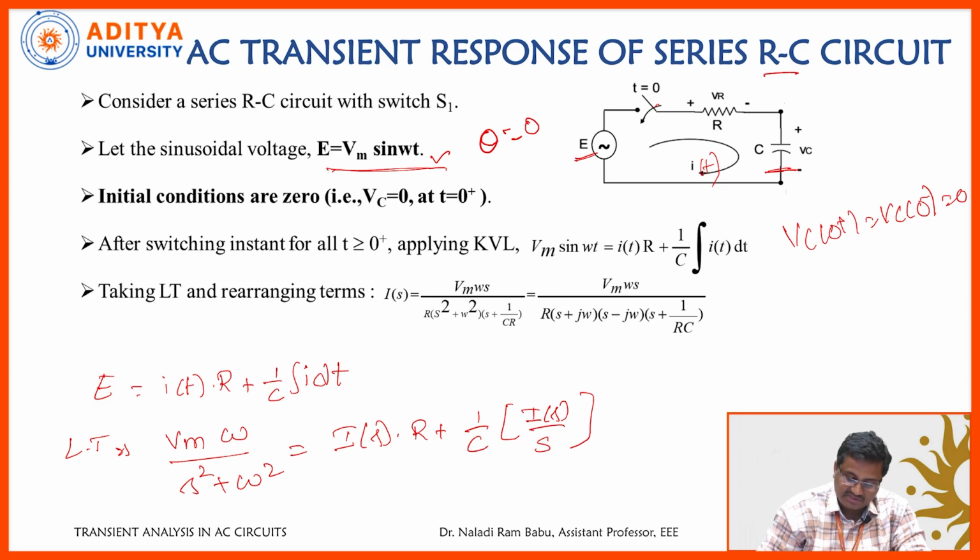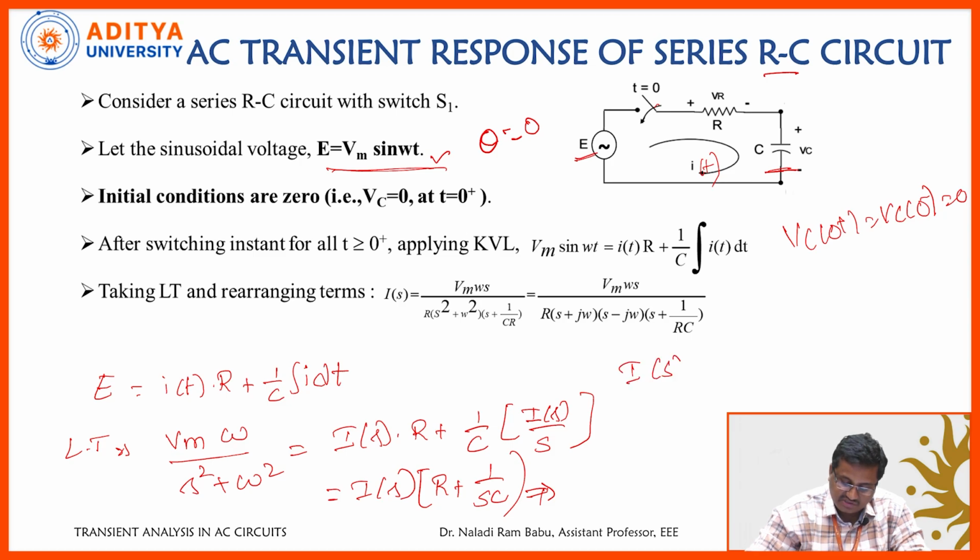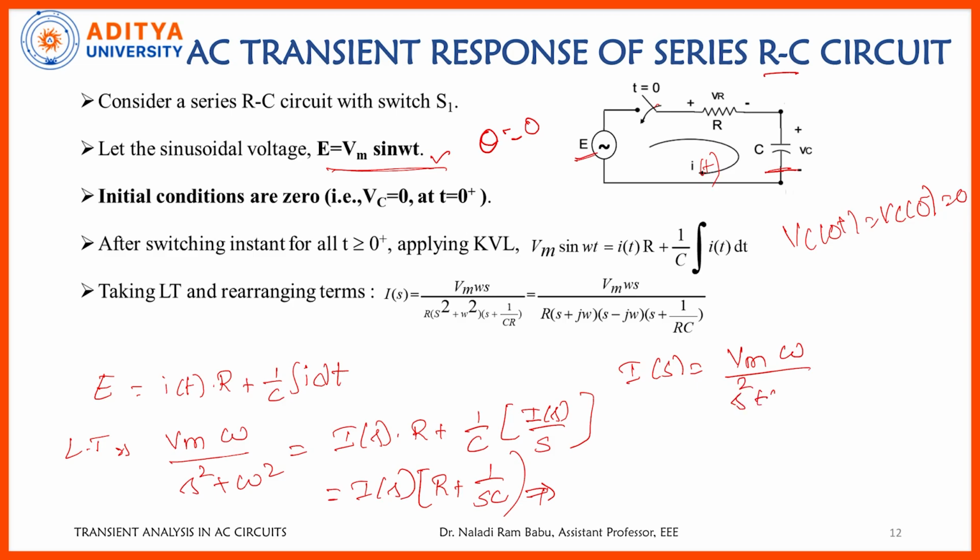Now from this expression, I am taking I(s) as common. It will be R plus 1 by sC. Therefore, simplifying further, I(s) is equal to Vm into omega by s square plus omega square into 1 by (R plus 1 by sC). In general, for applying the inverse Laplace transform, it should be in the form 1 by s plus a or s minus b, but here it is R plus 1 by sC. Now I am converting this to the s plus a or s minus b form.